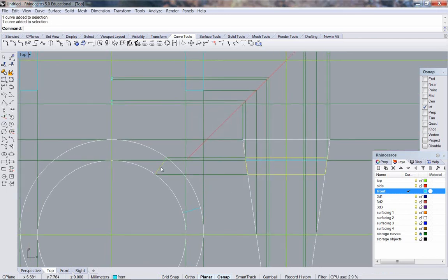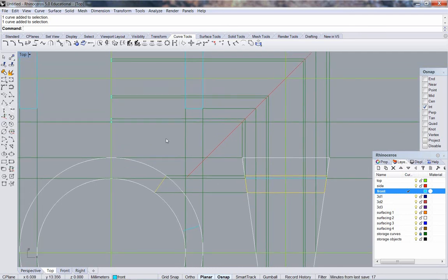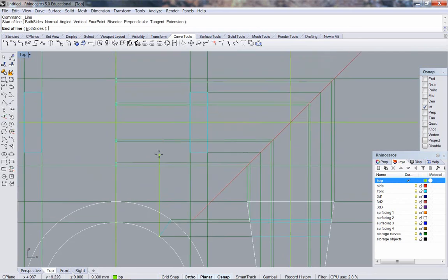So this is this. I'm going to now carry that information up into my top view. From front to top, take a construction line straight up at the ring bore, and I'll take it for the full width of the ring. Ring edge.